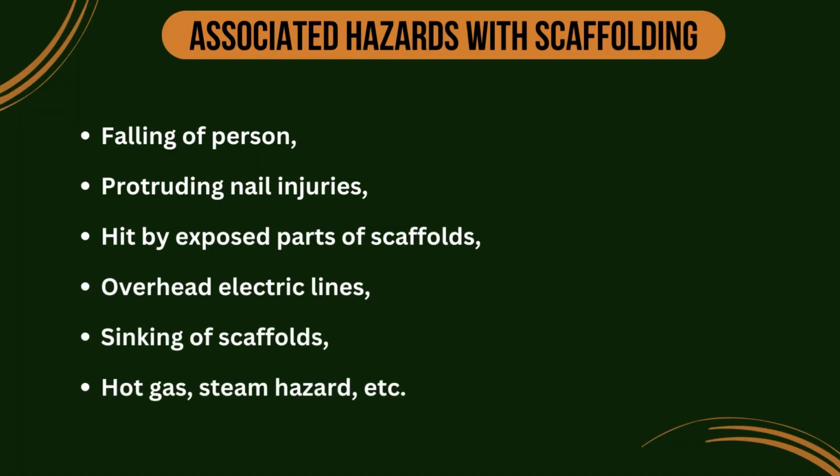Then sinking of scaffolds. Sinking of scaffolds may result because of loose soil on which the scaffold is standing. So before erecting our scaffold, we should first properly check the soil, whether it is loose soil or firm ground. We have to make our scaffold on firm ground so that our scaffold does not sink and result in some accident.